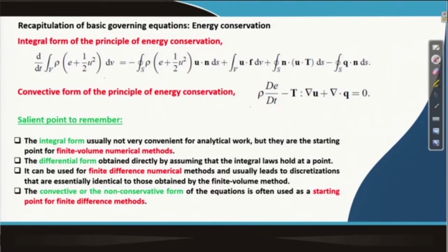And then when it comes to numerical solution, we have to recall that you can have them in integral form, which is often the form preferred for finite volume methods, or differential form, which is when you take the integral laws and apply them at a point, you come up with the differential forms, and those forms are more amenable for finite difference methods.